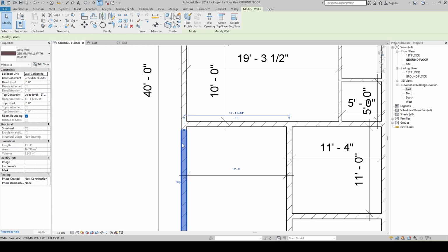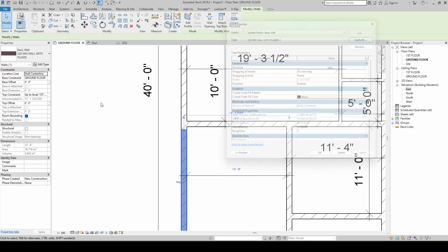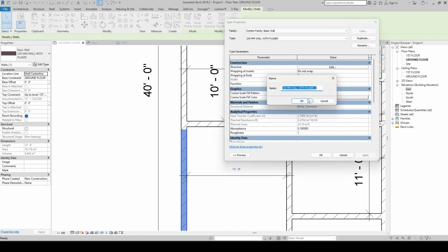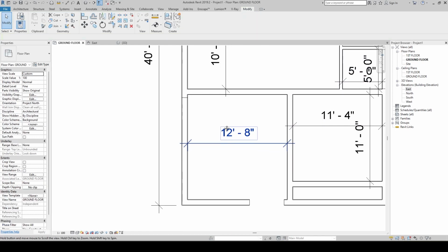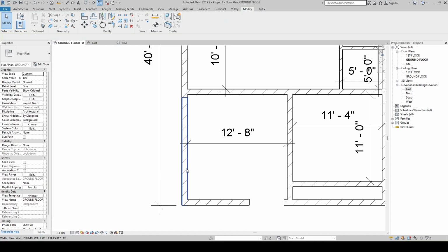This entire wall I'll make as a duplicate. I'll reduce the height of this. Once again, duplicate. Okay, it's fine. Now this wall has been duplicated. For this I'll reduce the height and keep it unconnected. I'll keep this height around 6 feet. Sorry, I'll press control A, 6 feet. I'll make it a compound wall.